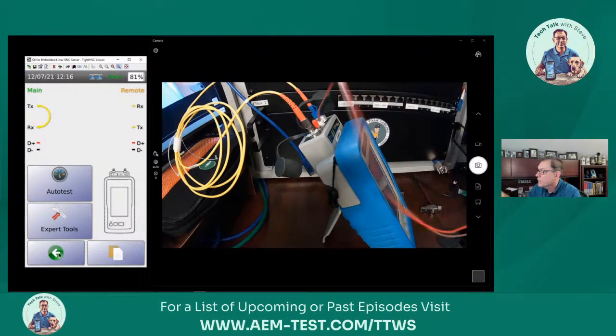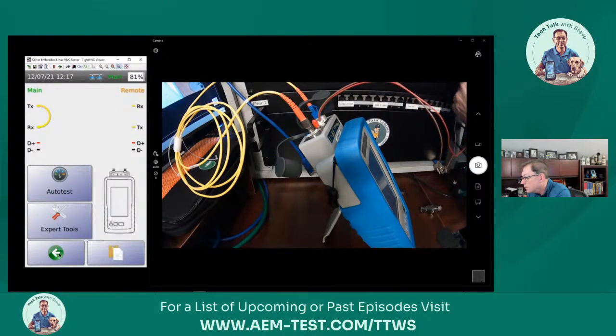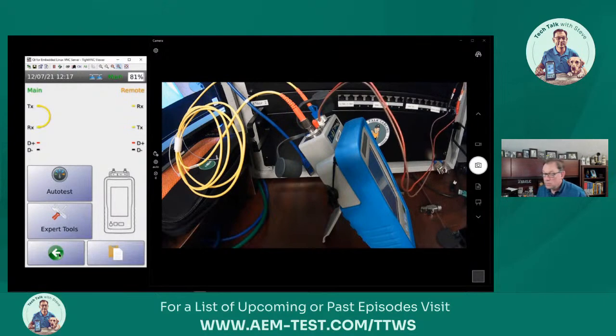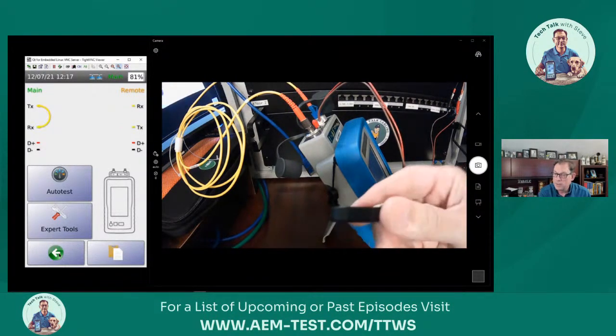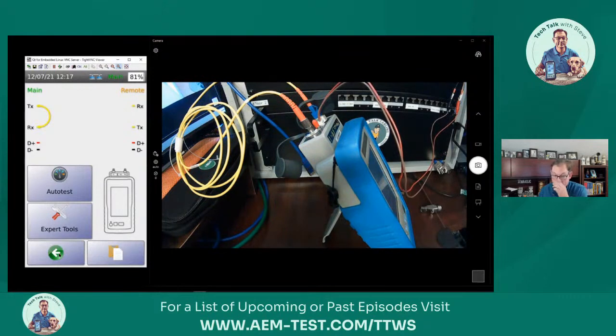So what I'm going to do is, I've got a piece of hybrid powered fiber, and I'm going to connect to my electrical conductors that are coming from that hybrid powered fiber. So we'll get that in place. And then we'll connect to a piece of fiber here, this hybrid fiber that has a loopback adapter, similar to the one I've got right here, just a little loopback adapter. So the fiber kit that you would get for these will include a loopback adapter for the remote end.